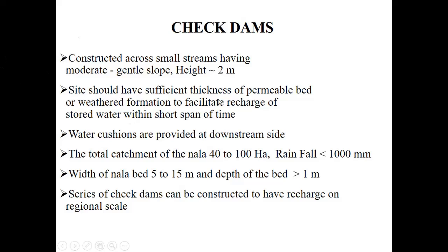The site should have sufficient thickness of permeable bed or weathered formation to facilitate the recharge of stored water within a short span of time. That means the aquifer should have a great porosity and a highly weathered system. So water cushions are provided at the downstream side.